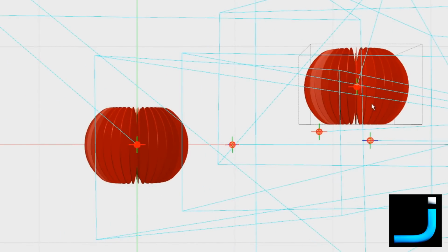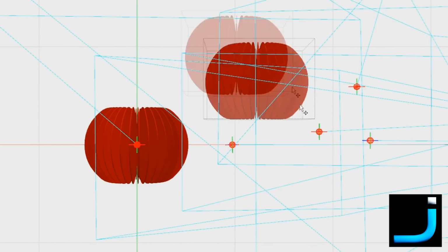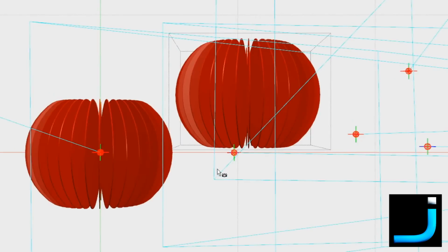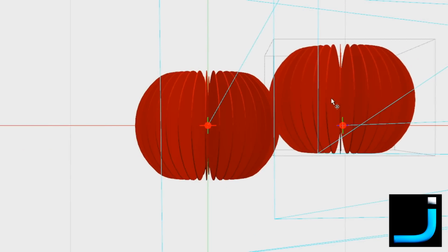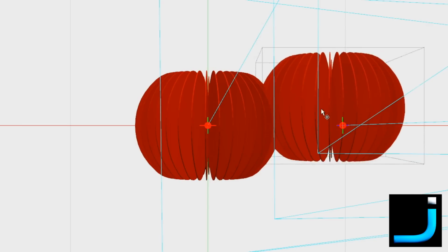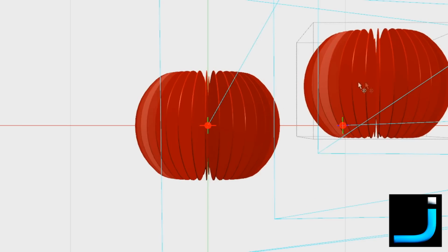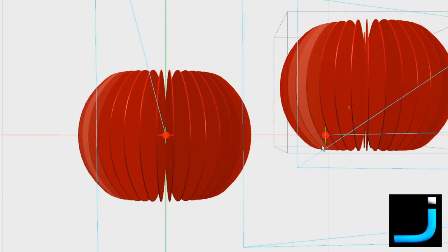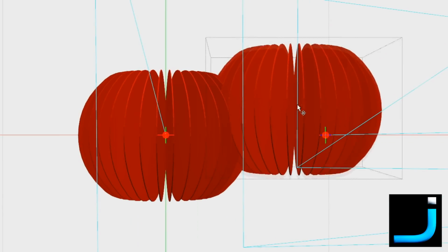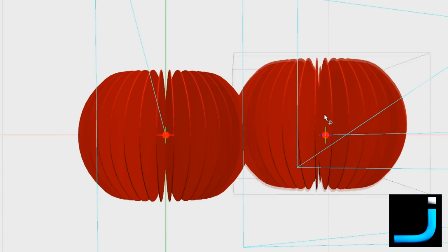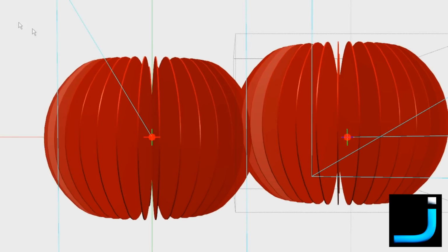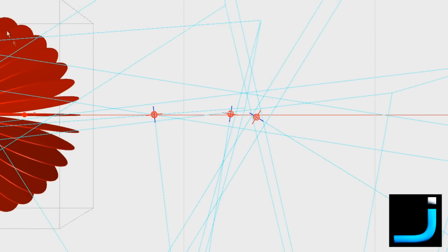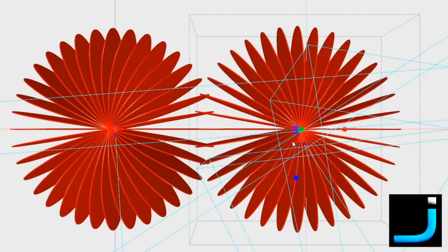We'll assume that here's your plane, and we fly around the sky. Assuming that the plane pattern is touching the ground station pattern, we're in range. If there's a gap between them, we're out of range, and therefore we're getting an awful lot of interference, or no video at all. So assuming they're touching, we're in range. Now, if we look from the top view, you will notice, and again, here's your plane.